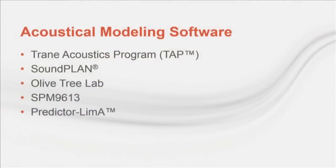Can software be used for an acoustical analysis? Yeah, there are several different software programs available to make predictive calculations. The Trane Acoustics program, or TAP, uses the source path receiver model for acoustic modeling. The user can enter sound power data, describe the sound paths, and TAP will provide sound pressure at the receiver location. So let's use TAP to make a model of the air-cooled chiller next to the parking lot and practice fields. I'm going to move over to the monitor and demonstrate how simple it is to make this predictive model.